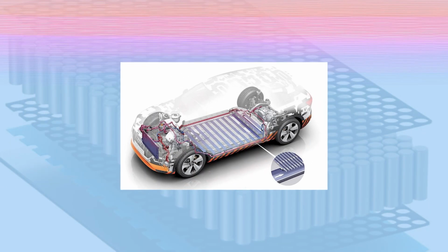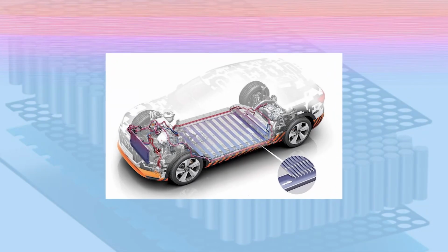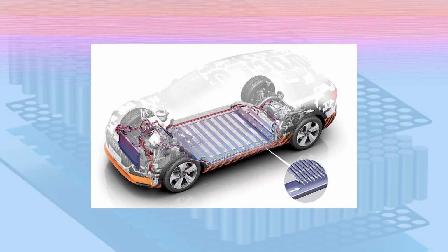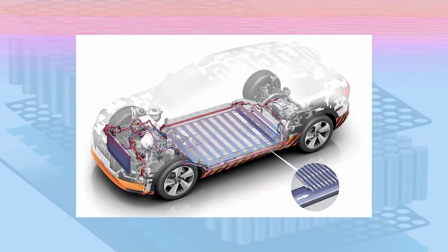So, the various aspects which are to be considered when we design the thermal management of a power electronic converter or inverter are: the first one, the space availability; the next one, the power rating, or the heat or the temperature that is being dissipated when it is under peak power operation; and the third and important one is the frequency and the current that is flowing, the current rating of the converter.